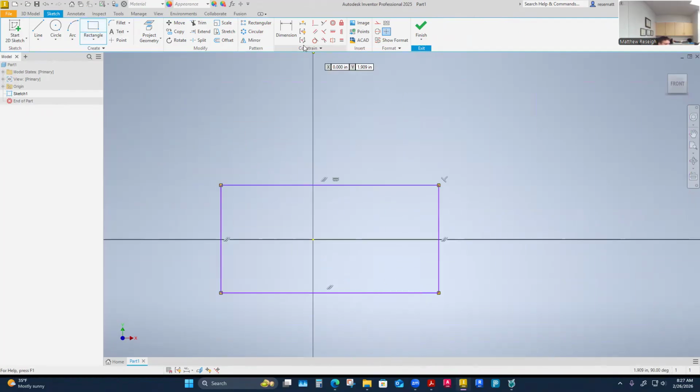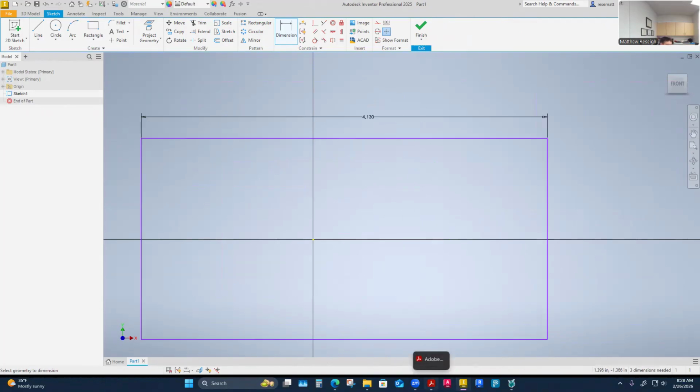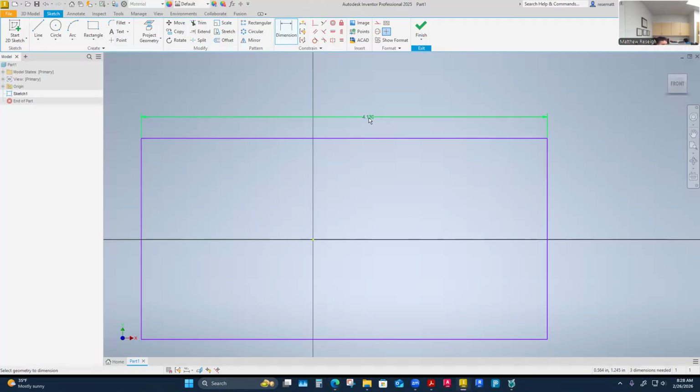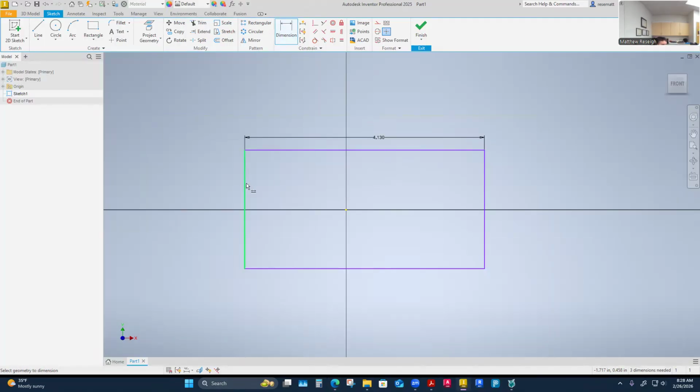A rectangle part that, if it was 3 decimal places, would probably read out as 4.125, but 4.13 is what it's called out as on that drawing. I'm just interested in what the tolerances are here. I guess most of them are 3 decimal place. I wish I had changed that to 3 decimal place. I'll leave it like this so you can recreate this. Everything else is 3 decimal place. I almost forgot to bump that one's accuracy up, and it would probably be 4 1/8 if I think of nice round numbers. But I will leave it at 4.13 because that's what it is, and that's probably what you do too. 2 1/4 this way.